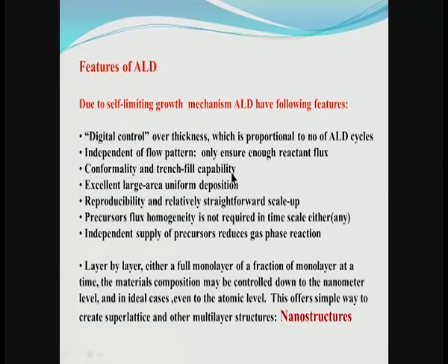So, what are the features of ALD? To summarize, due to self limiting growth mechanism, ALD has the following features: digital control over thickness, which is proportional to the number of ALD cycles, as we already mentioned. It is also, unlike CVD, independent of the flow pattern of precursors.